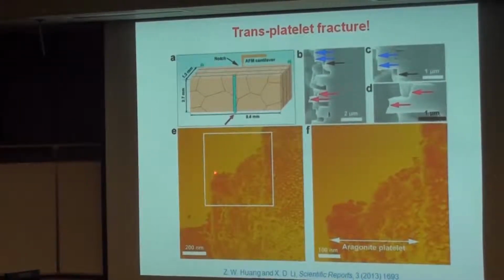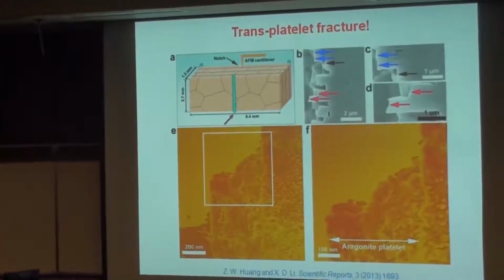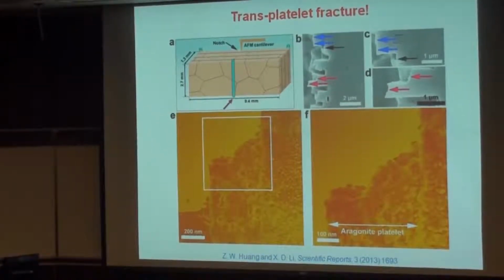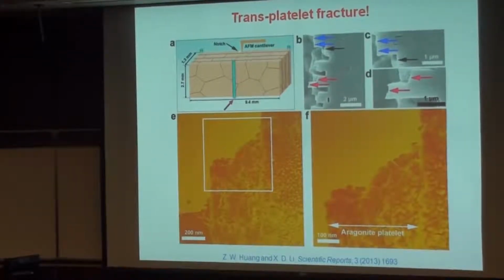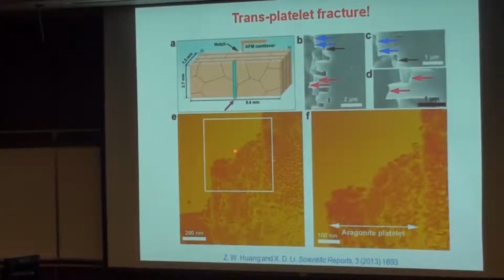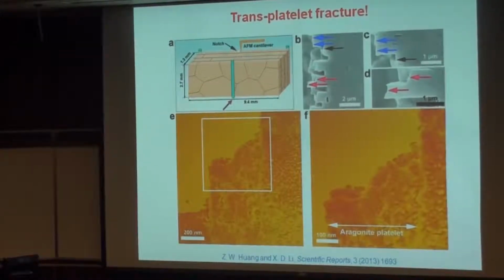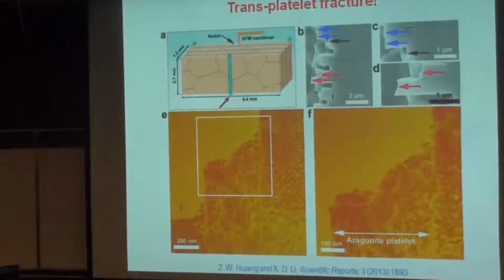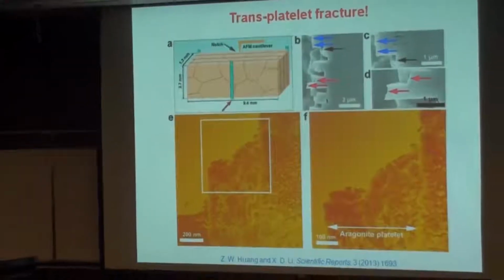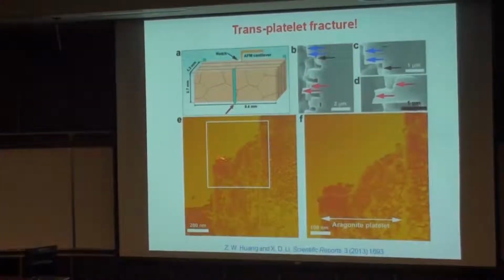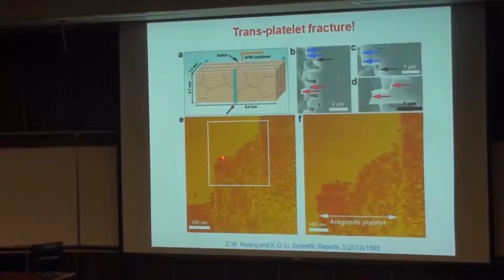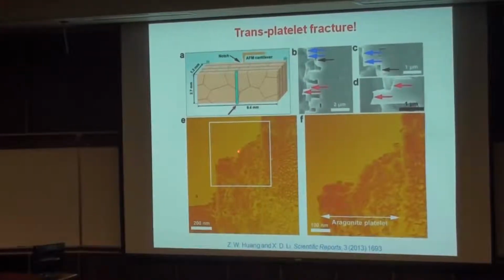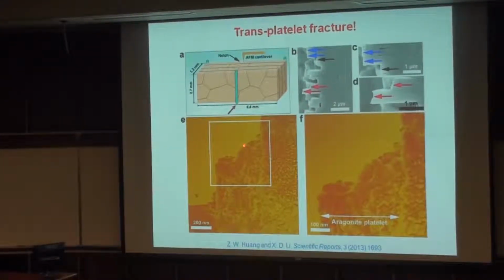And when the stress is high enough, and the deflection along the biopolymer layer is difficult, the crack actually jumps into individual bricks. So you see this is a crack path in a zigzag manner along the particle interface or the biopolymer layer inside individual bricks.